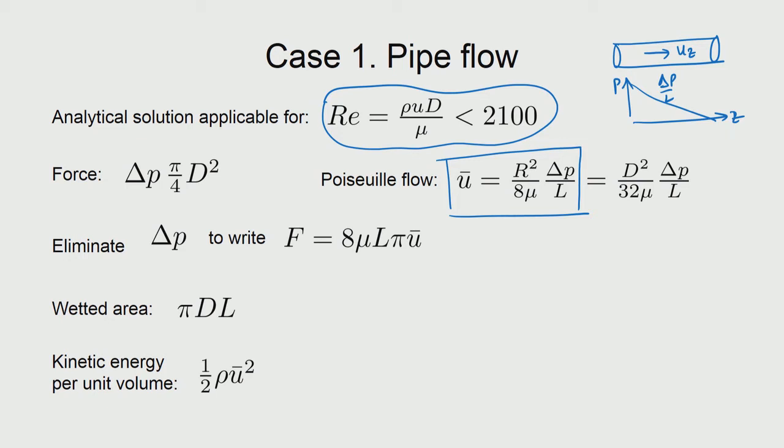So, the whole idea is what do we do about that number. That is where we are headed, and let us see, for the range that is valid, how the friction factor appears using the method that we have seen. What we do basically is look at the terms that we have taken up. The pressure is delta P, over which the entire domain is experiencing the driving force for flow, into the cross sectional area over which the delta P is acting. So, that becomes the force term, and the solution of the average velocity is already given here,